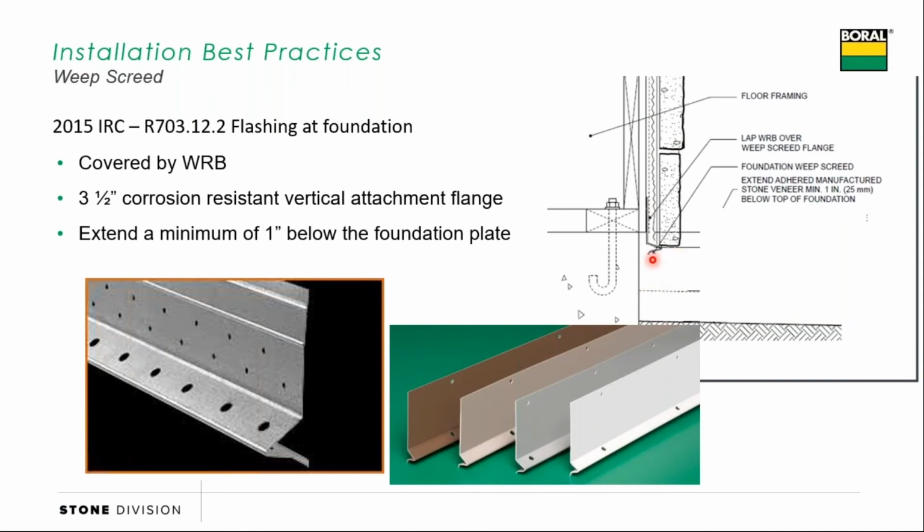The other primary purpose is a capillary break. We want to make sure that water doesn't wick up into the bottom of the wall system. The papers that are in behind our stone are meant to handle water for days, weeks, sometimes at end, but eventually to dry back out. When we bury stone down into grade, water begins to wick up inside of our stone, and now water is being held against those papers for much longer than they're meant to stay wet. They eventually begin to deteriorate, and now water can begin to get into our wall system.